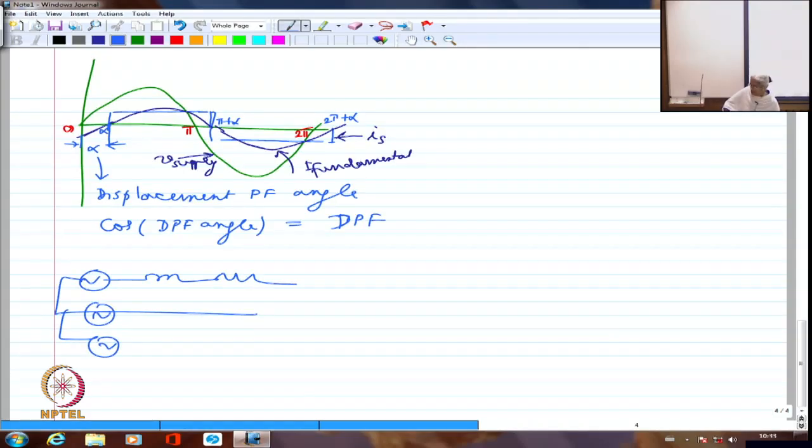If it is three-phase, everywhere I will have some transmission line impedances. All these are going to carry this harmonic current. So R multiplied by the harmonic content of the current will give me some harmonic voltages, whether I like it or not. So there will be a lot of harmonic voltage generation. Although my generator, poor fellow, is trying to generate a purely sinusoidal voltage, I have generated all these harmonics.